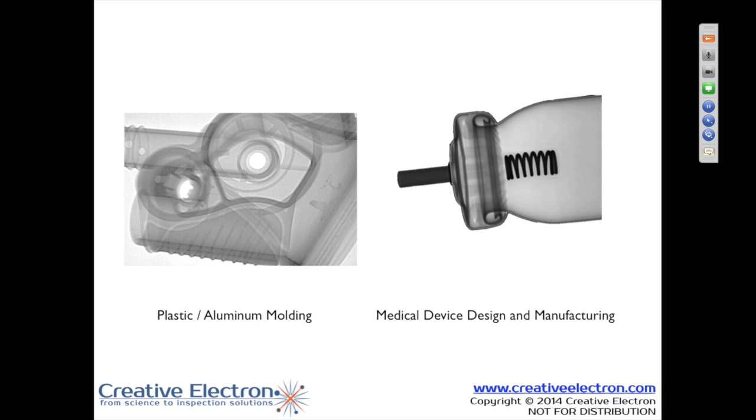The database would also allow you that if you did x-ray this product prior to shipping it, it would give you an indication of maybe that spring has dislodged, maybe something's changed in the seal. By being able to look up with keywords and with tags and operators as well as dates and serial numbers in the database, you could pull that image up and compare it with the current image of the product that came back. And you can look at it and it gives you a better understanding of what may have happened in the field. So the database function is really huge, and that is a major move forward in the use of x-ray in manufacturing in general.